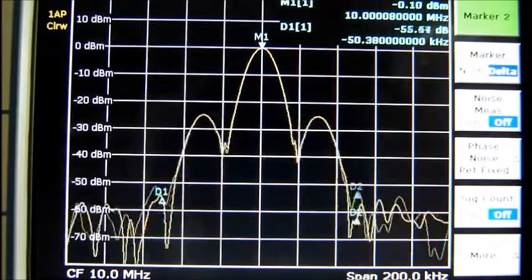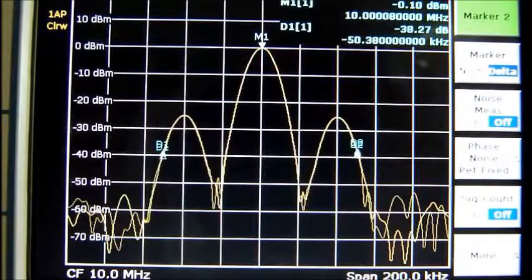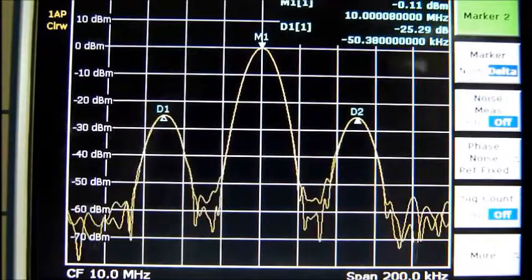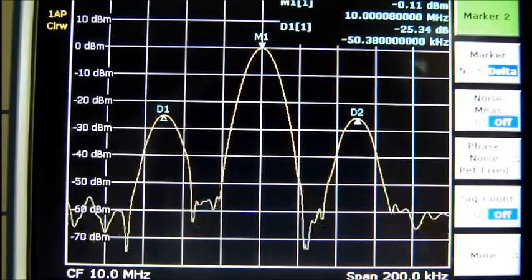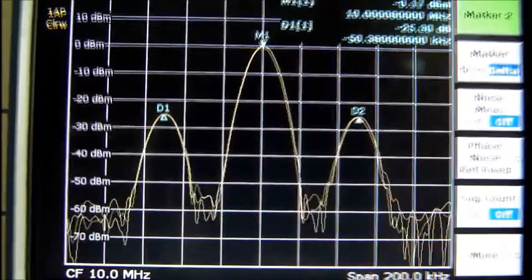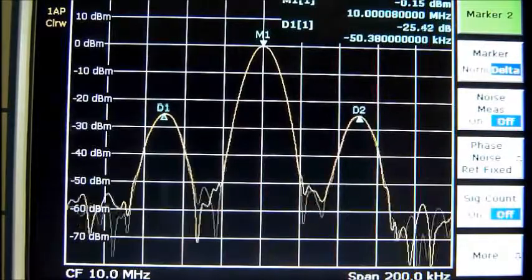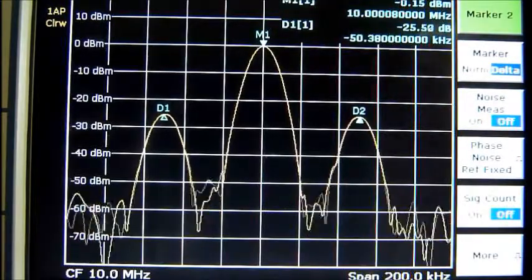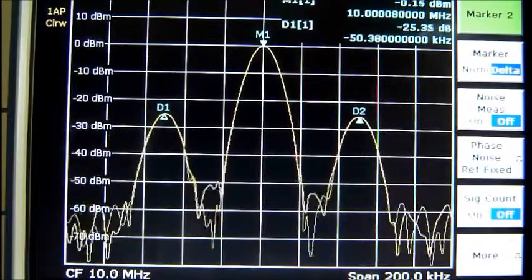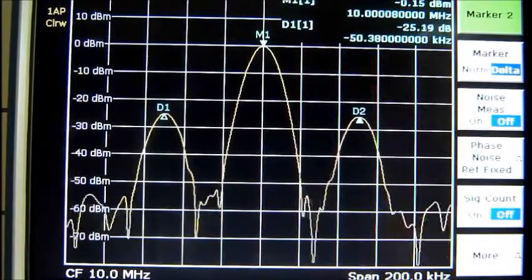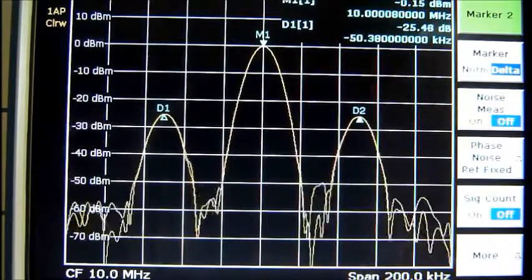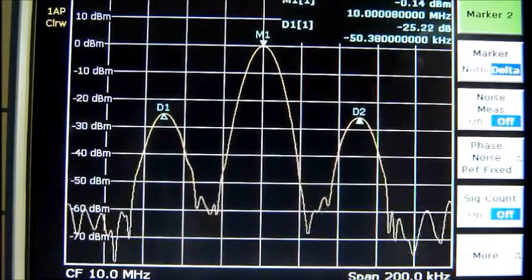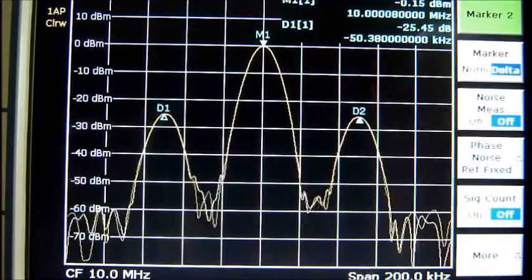If we start increasing that frequency back up to 50 kHz, we see how the two sidebands spread away again from the carrier frequency. Now we will look at the effect of varying the modulation index over the spectrum of our transmitted signal. The modulation index indicates the coefficient or relation between the power of the information signal versus the power of the total signal transmitted.